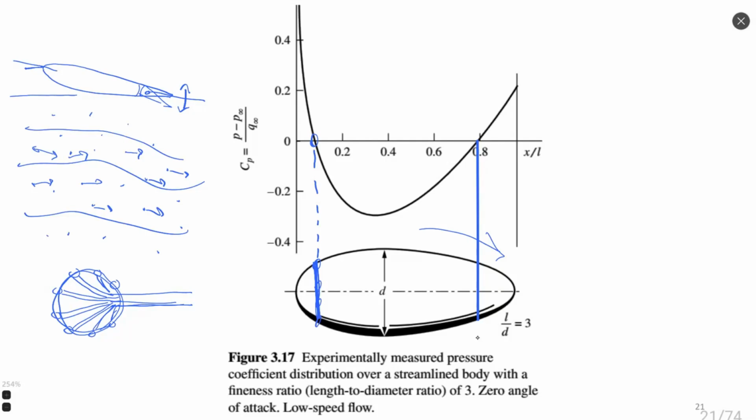So, for example, if flow blows from some direction, we will measure bigger pressure at a point close to the stagnation point and smaller pressure at a point on the other part, and very small pressure far away, right? We know the distribution of pressure in case of a sphere is quite well explained. So when our sensors detect such a distribution, using a mathematical model, we can predict angle of attack and direction of flow, just analyzing several discrete points where our pipes are installed.